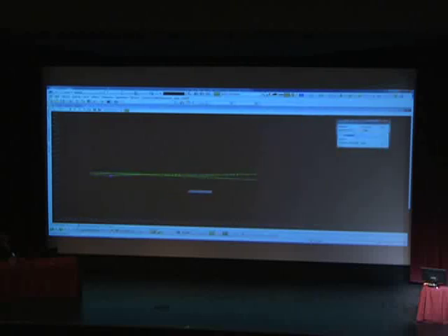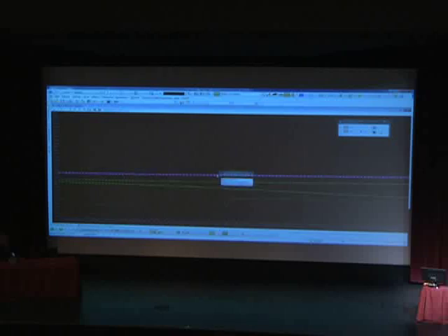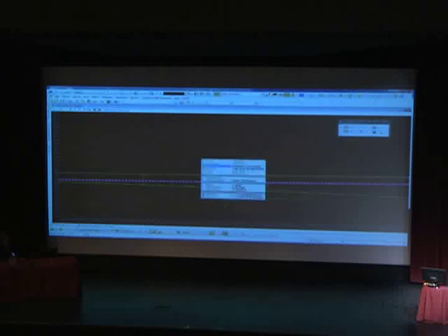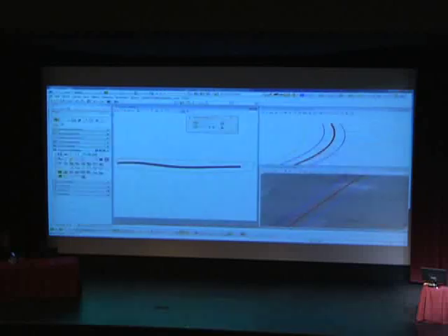I'm going ahead and complexing that line now into one single element, and I'm going to set it as active. Also, I'm going to have to put this on my profile sheets, right? So I have to export it to my GBK because I'm going to be using my DNC manager to draw out all the alignments and profiles. So I gave it a feature name of ditch bottom. Then I'm just showing you right here under the properties display, it shows you the rules associated with those lines. So this one's showing you it's a 2 foot offset from my edge of pavement. And there you go, now I have a ditch line created.